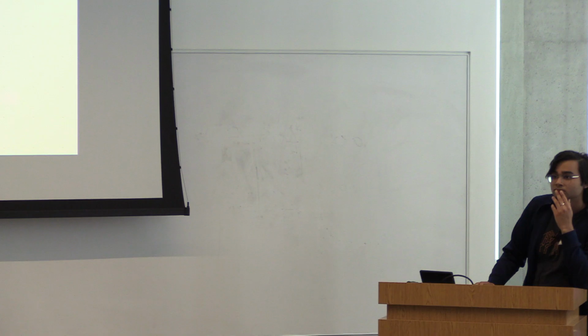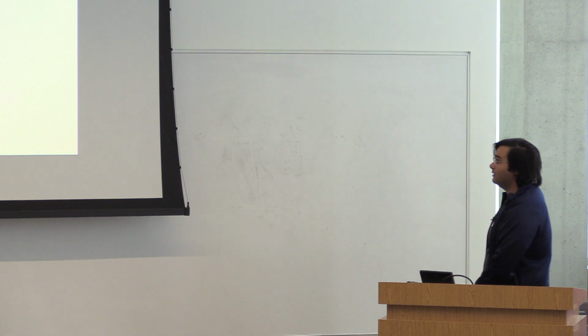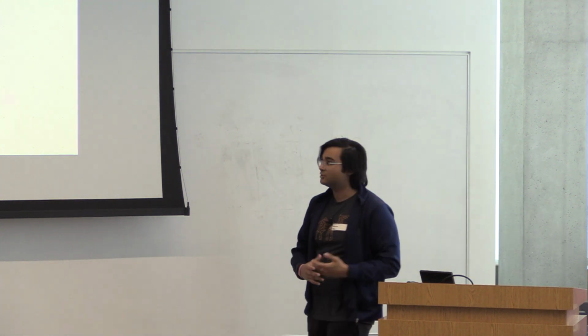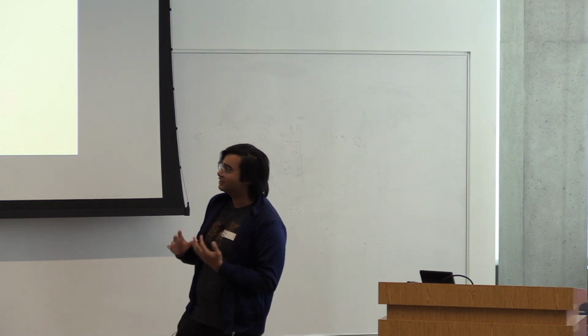In your slides, you said circuits are computational graphs, but I believe it's computational graphs with states. Mm-hmm. So can you briefly explain that? Yeah. So the question is, I showed you this nice lie about pure computational graphs. You just compose them and you're done. But really, circuits have state, and that's the other part of the equation I didn't show you. Hopefully, you can believe me on faith that you can define registers in the same way and compose them together.